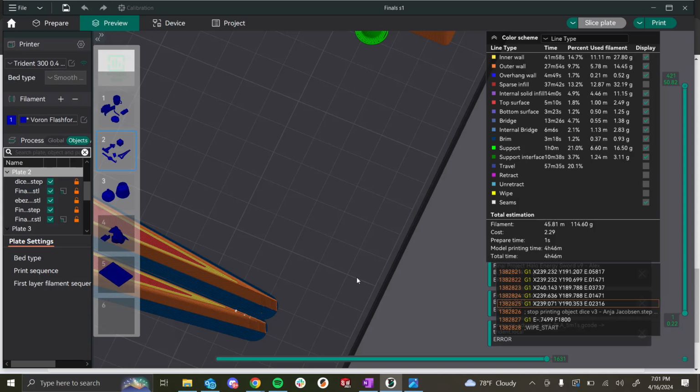Yes. So there's a unit on the back that connects to 8 different spools of filament. It could be different materials or different colors of the same material. The printer will go about its business. It'll print, and when it wants to change colors, I'm gonna have a filament cutter on my print head. So it'll go to the corner, snip the filament, pull the old filament out, put a new one in, and then continue printing. And it'll do that thousands of times until you get a print.